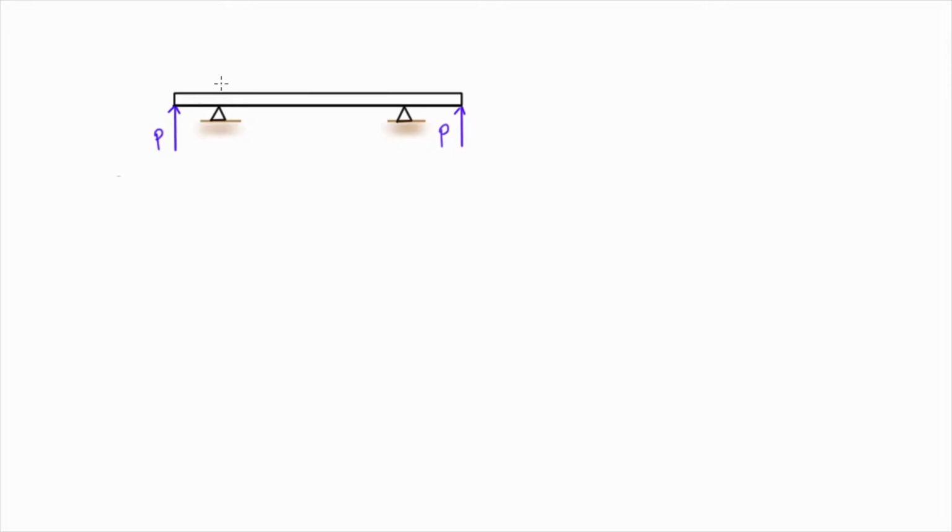And pure bending is what the middle of this beam between the two reactions here is going to be undergoing. So if we load a beam like this that's symmetrical with these equal loads on each end, then we're going to get a free body diagram that looks like this, where each of the reactions obviously has to be equal and opposite P here, and it's all symmetrical.